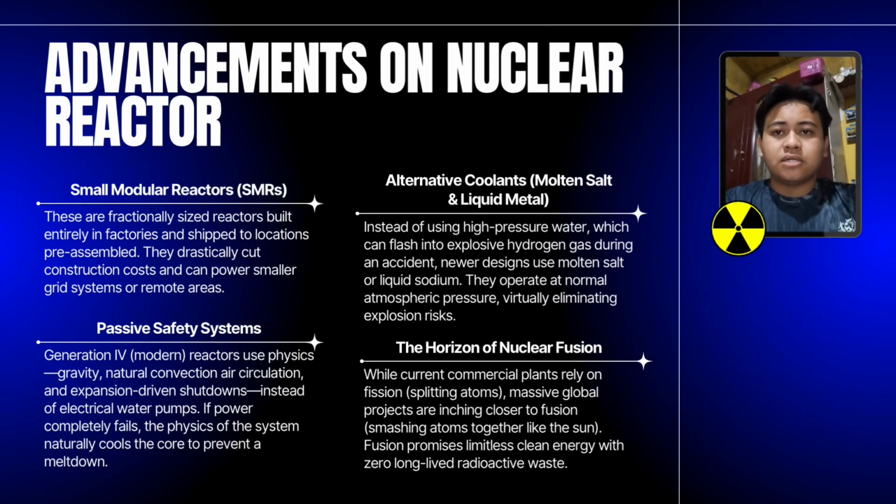Third is alternative coolant, that is molten salt and liquid metal. Instead of using high-pressure water, which can flash into explosive hydrogen gas during an accident, newer designs use molten salt or liquid sodium. They operate at normal atmospheric pressure, virtually eliminating explosion risk.